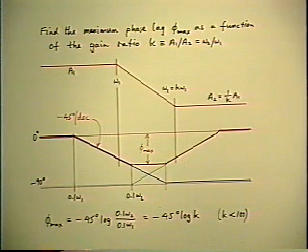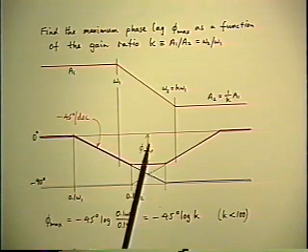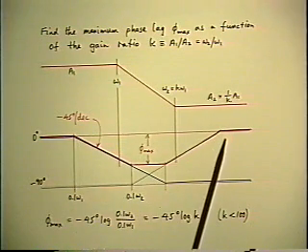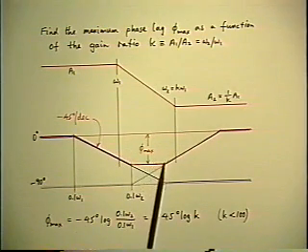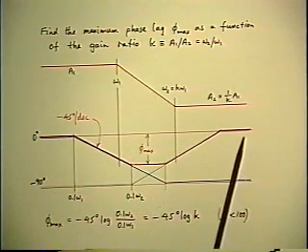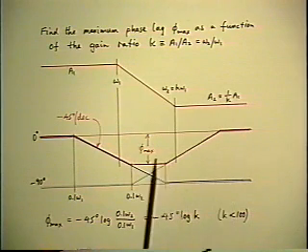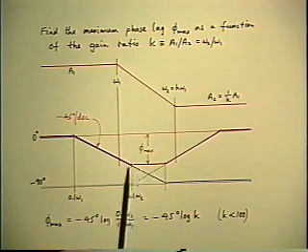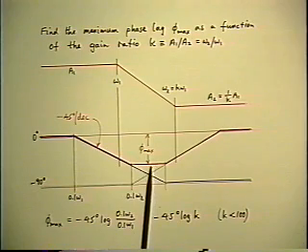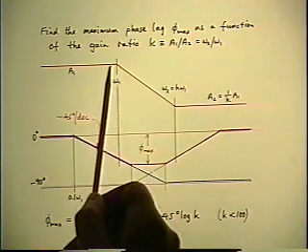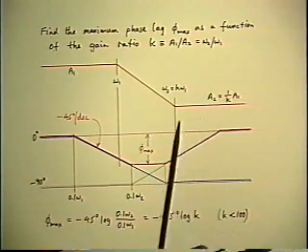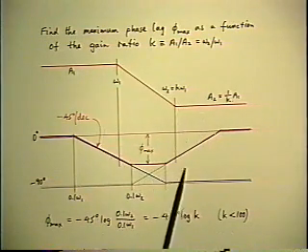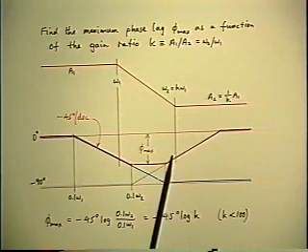And in that application, the most useful thing to know about the network is that it's not free. You do get some phase lag, but only temporarily until you get beyond the second corner. So an important thing to know about this network is what is the maximum phase lag you get as a function of how much gain you need to throw away. So that enables you to set up a very simple little isolated problem.